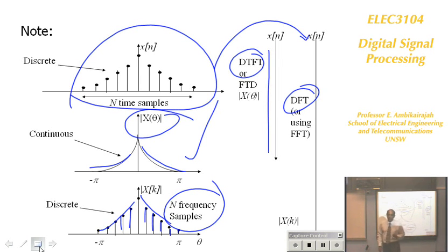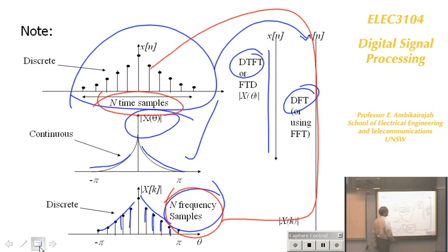When you do the discrete Fourier transform, we will always assume, and also we can prove, that the number of time samples you take to get the FFT gives you the same number of frequency points. For example, if you say I'm taking N time samples, you will find you end up with N frequency samples when you come through this technique. So if I took 100 time samples, you are then looking at 100 frequency points.